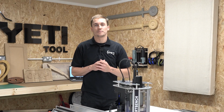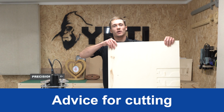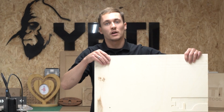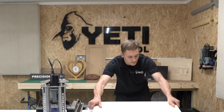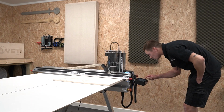Before starting your job, we recommend doing some test cuts in some spare pieces of stock to check that there aren't any problems with your cutting parameters prior to starting your job. This is worth doing because it will help you determine whether the target load you've chosen is suitable for what you're trying to achieve. You can adjust this if needed during the test cut until you're happy.